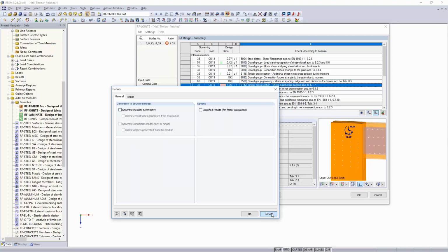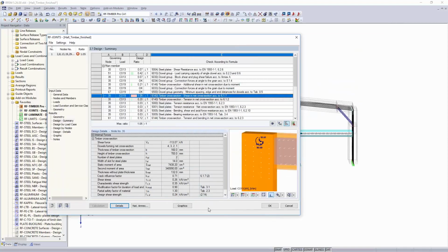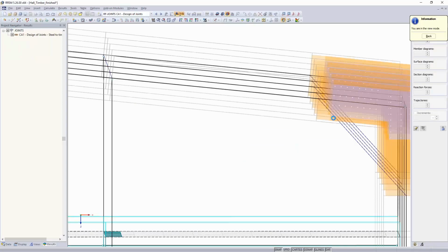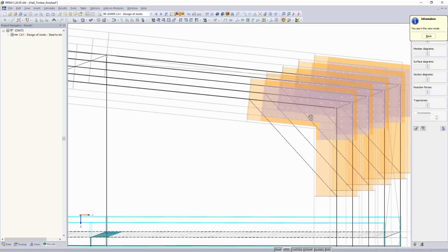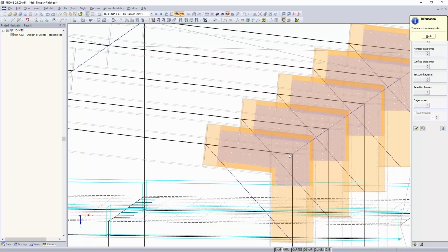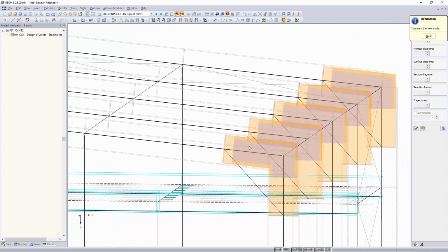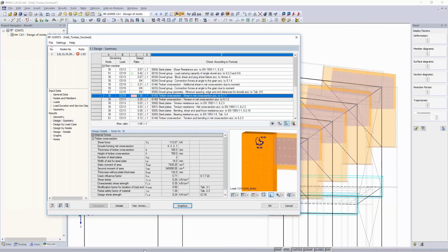Right now, when you look at the structure, we can do that in here. There is still this connection assigned, okay, for sure. But it is still this moment hinge here with a value of 0, and this beam or this member is connected to the corner point. But if you look at that in more detail, you would say that it's probably connected via all the dowels, and here is actually no connection. So the static system that we are designing in here is actually wrong.